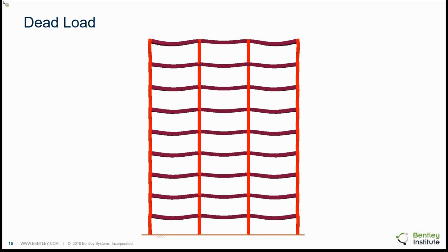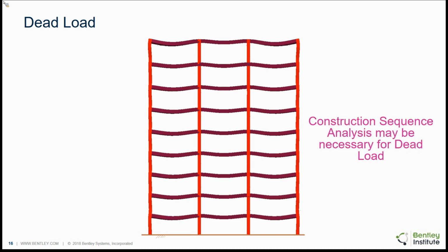But that's entirely different than the way we looked at live load, and that's entirely different than the way we analyze structures. For the dead load, it's not the case where the entire structure is in place and then we turn on gravity and suddenly we get all this displacement. It's actually applied step by step or stage by stage. And so what we call a construction sequence analysis, an analysis taking into account these steps, may be necessary for dead load, certainly something that needs to be considered.